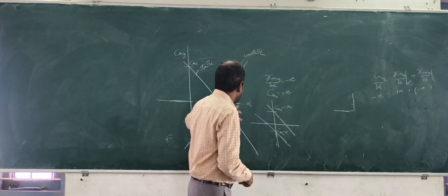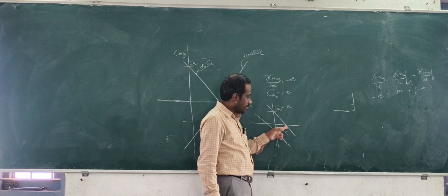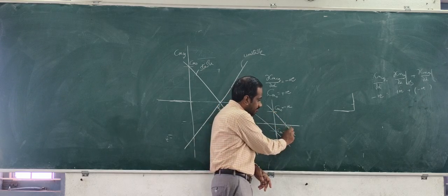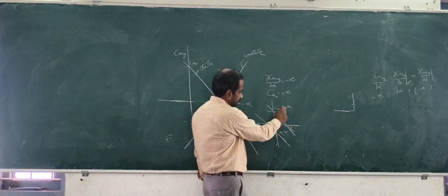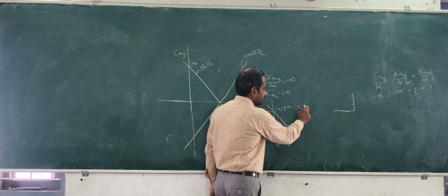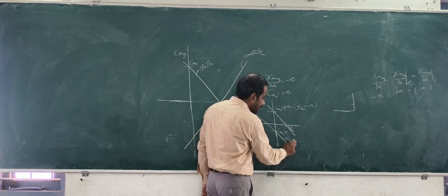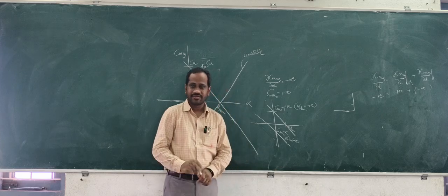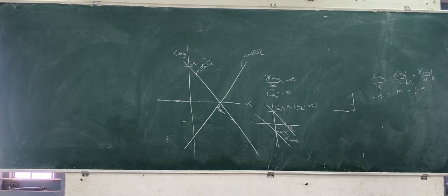In this case, at what angle of attack is the aeroplane balanced? The balancing, or equilibrium, angle of attack is alpha trim. Here alpha trim is positive. Here alpha trim is negative. Stable only. The aircraft will always look for a balancing angle of attack that is negative. Still stable. It doesn't question anything about stability. It questions the equilibrium angle of attack.